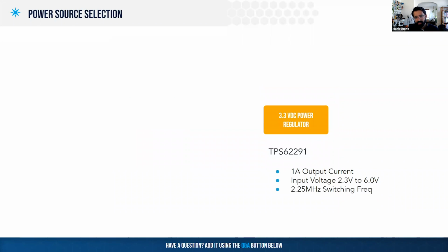For today, we'll be using, again, a Texas Instruments switching regulator, just to make things more interesting here. The reason we chose this particular regulator is because it's already in our supply chain. You may have a bigger design that uses a 3.3 volt rail. You can just derive power from it, so it's up to you. These days, regulators are getting fancier with built-in power inductors and whatnot. Torex makes these tiny one-package parts with built-in capacitors and inductors. You may want to try that, but we'll keep using what we have just because supply chain would be happy with this.